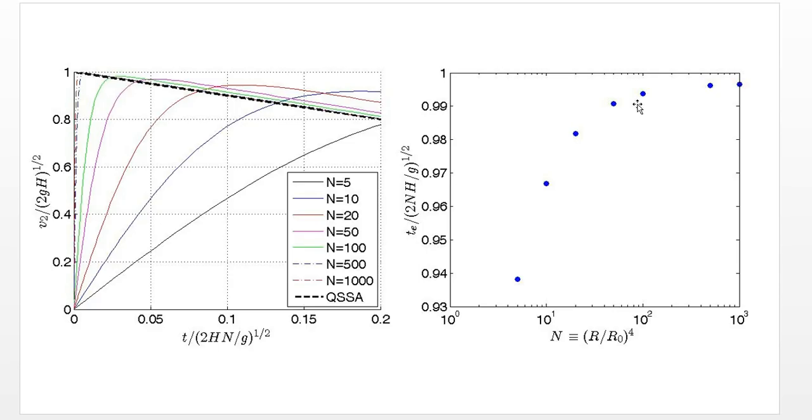And once the hole is about 2.7 or 2.8 times smaller than the radius or diameter of the cylindrical tank, the efflux time is within 1% of the value predicted by the quasi-steady state approximation. And we can see how much more effort there was in using the full form, the unsteady form of the mechanical energy equation, which necessitated, in this case, a numerical solution as well, versus the 5 or so minutes it took to do the algebra for the initial problem using the quasi-steady state approximation.